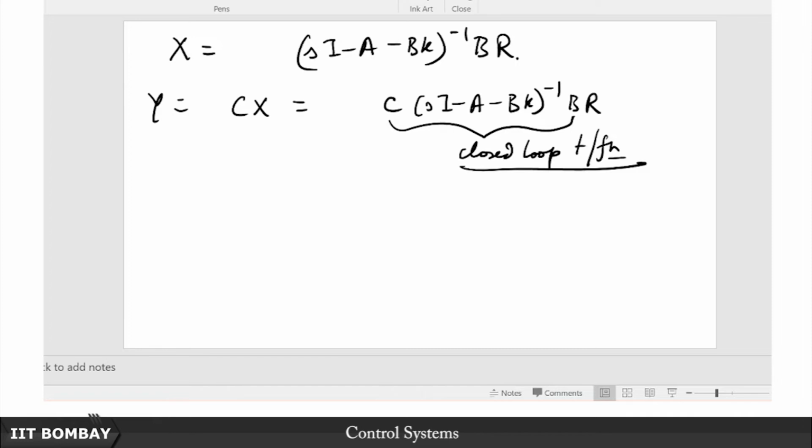As you have now seen here, we have got this transfer function, the closed loop transfer function. We managed to prove to you that not only can the poles of the controller and observer be designed independent of one another, but also that the observer does not make its presence felt insofar as the transfer function from the reference input to the output is concerned, yeah. So that is one of the greatest achievements, now you can safely say, of modern control theory, because now you no longer are dependent on having to tap in to the states in the middle of the design of the plant, in the wiring, right.